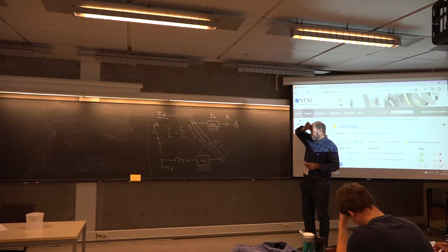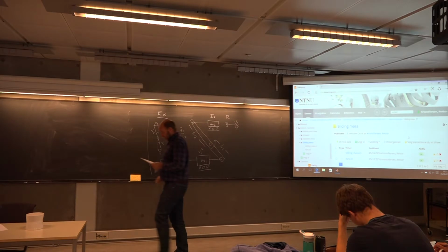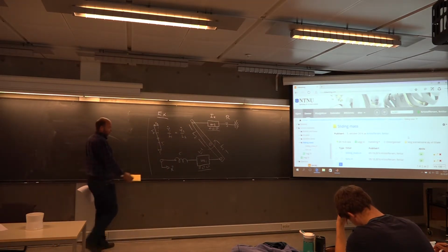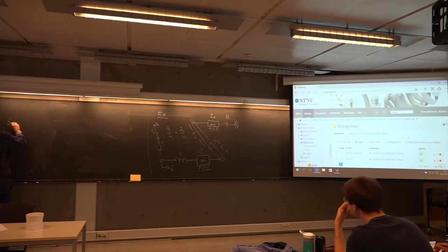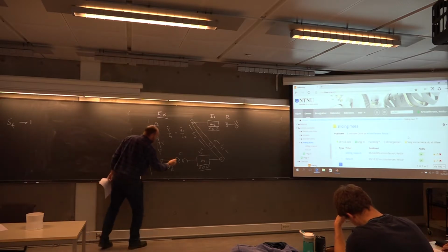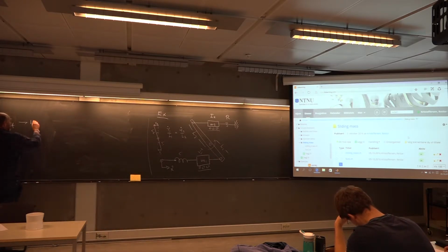So let us now try to draw a bond graph for this problem. Starting to the left, down here I have a flow source. So that should read something like this. It hits a one junction first, this point, but this point has no mass, so this one junction is going to disappear anyway.